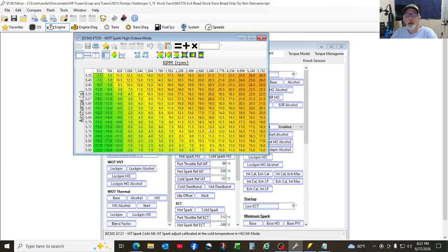And it's not like you go nice and smooth back. It's just a boom, slam, boom. Okay. And your tach just drops. You slam those brakes on, your tach's going to drop because your torque converter is still locked up. It hasn't had a chance to unlock yet. All that stuff can be 100% totally damaging to your engine.